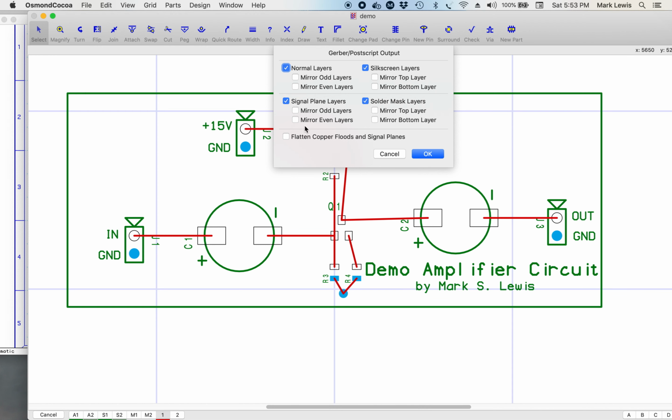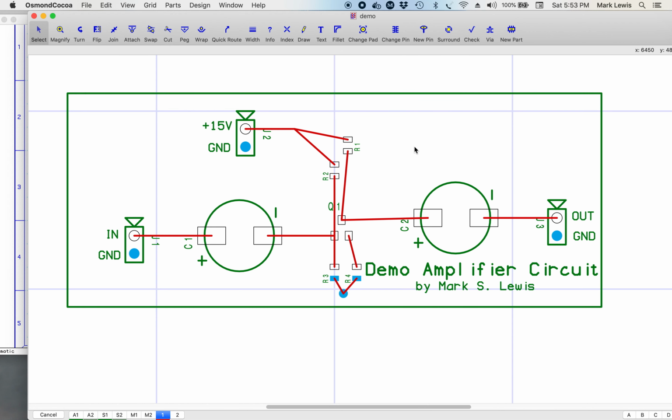And it will generate some files, and they're going to be in a folder, and you'd zip them up, compress them, and send that through the website or email or however the circuit board house wants them, and they will know how to make these circuit boards. Often they do them in batches. Sometimes they might say a minimum order of 5, and it could be as cheap, depending upon where you go, as for a 2-layer board, 5 of them for like $4 or $2 or whatever. Sometimes they have specials, but even at 40 cents to $1 a piece, that's really super cheap.